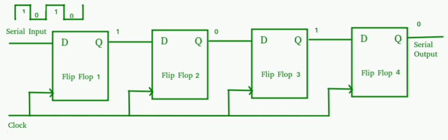Parallel in, serial out. To store parallel in data, if we store n bits, then the number of clock pulses required is equal to 1 clock pulse. To get serial out data, if we store n bits, then the number of clock pulses required is equal to n minus 1. Note: to convert temporal code into spatial code, we use a SIPO register, whereas to convert spatial code into temporal code, we use a PISO register.